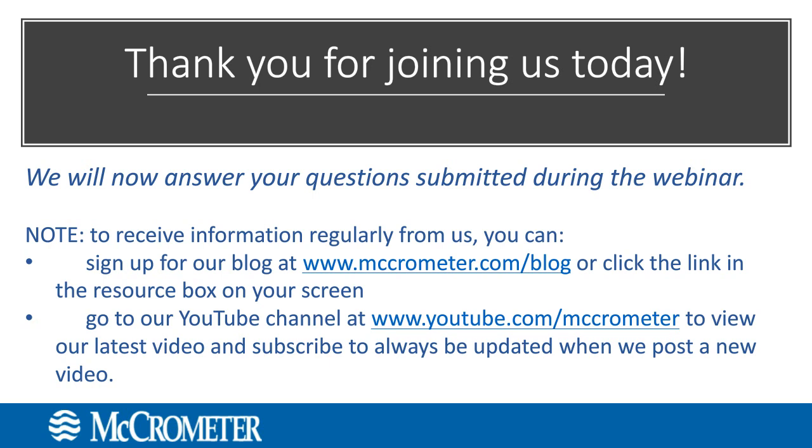Now, I think the big question that people ask about it is, do you really want to calibrate an orifice plate? I noted earlier that typically orifice plates are sold uncalibrated, the price of calibration can far exceed the cost of the orifice plate itself. So it's really a question of, our VCones come fully calibrated as they are. So yes, the orifice plate can achieve a similar accuracy to the VCone, but the question being, do you really want to calibrate an orifice plate? And that's up to, obviously, the customer to decide.